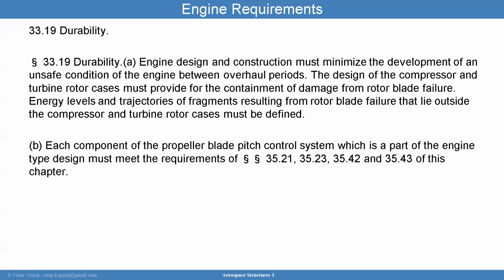Durability for engines, you want to make sure that the engine design and construction must minimize the development of an unsafe condition of the engine between overhaul periods. The design of the compressor and turbine rotor cases must provide for the containment of the damage from a rotor blade. And there is a YouTube video you can watch where a blade is being broken on purpose to see if the engine can sustain that.